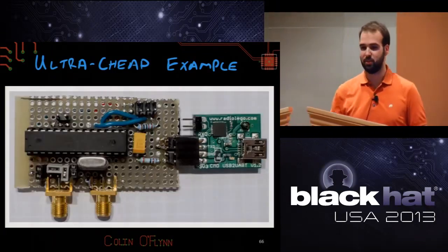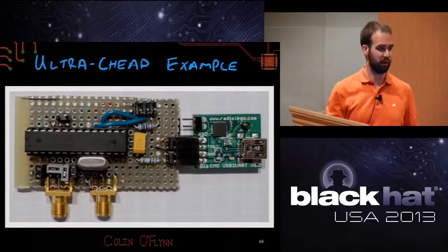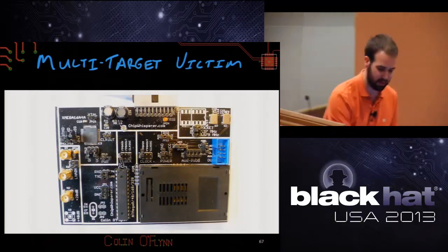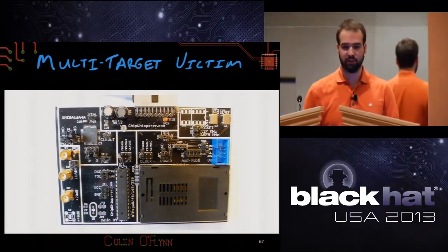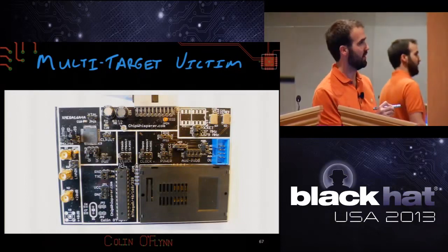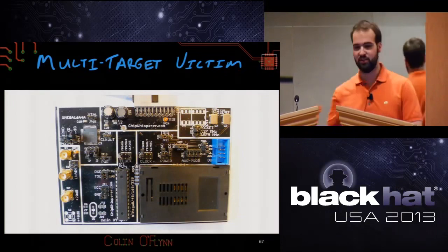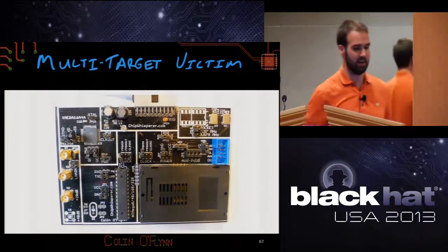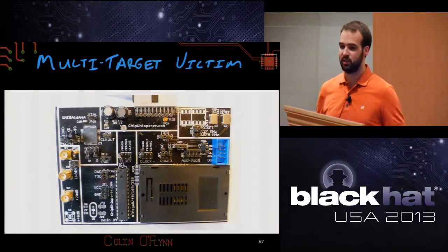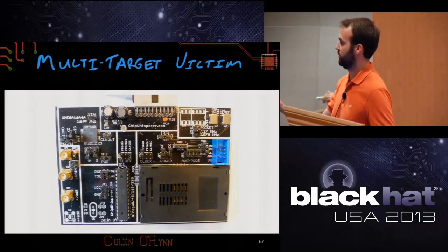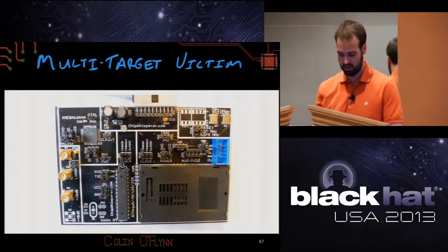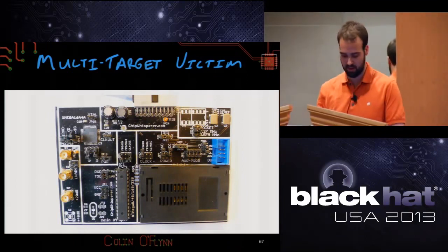And in a similar way, you could build this onto a physical board if you wanted a platform. Or something newer and better that I have here is what I call the multi-target victim. The multi-target victim has a board designed with this microcontroller on it, that same one you just saw. It also adds in some other options. This XMega device is a hardware AES engine, and there's the familiar smart card type interface, so you can work with smart cards once the software supports that.